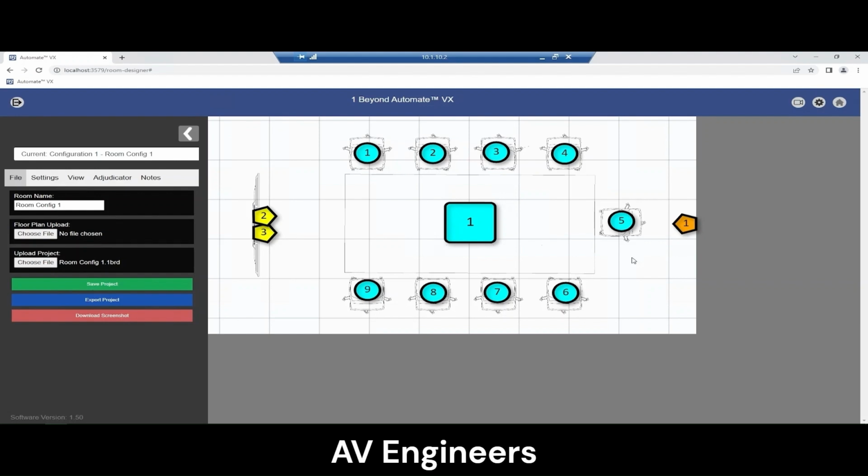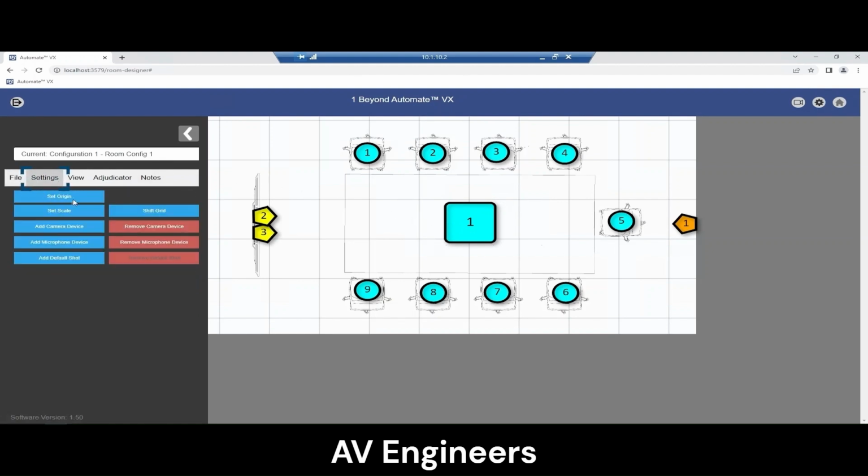Then, you can use the Set Origin tool in the Room Designer to pick an origin point in your room. All measurements are calculated in inches or millimeters if you're using metric. Click on the Set Origin under the Settings tab, then drag the red dot to the point on your floor plan that you'd like to measure from.